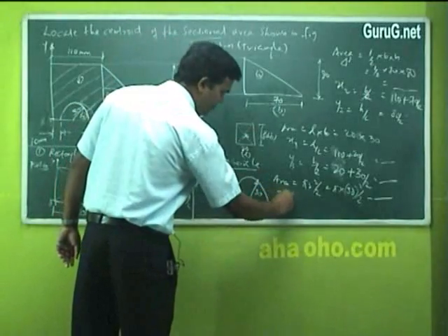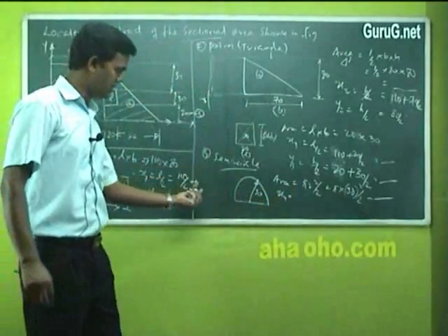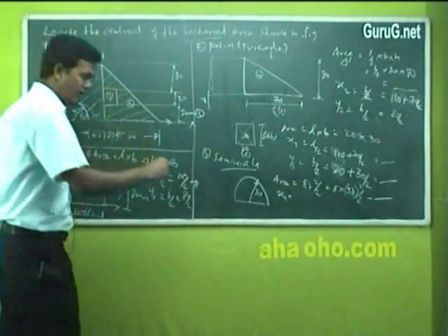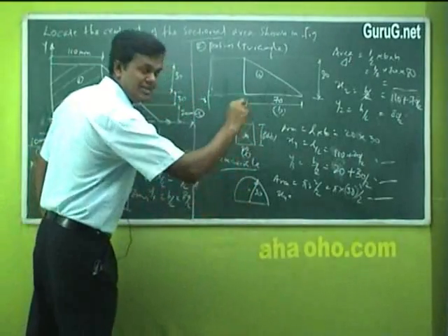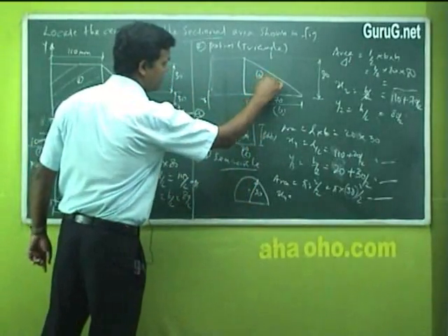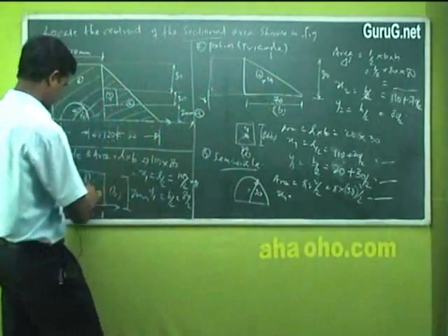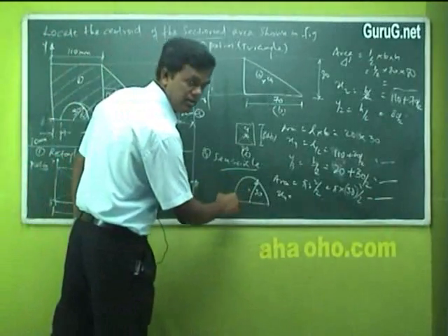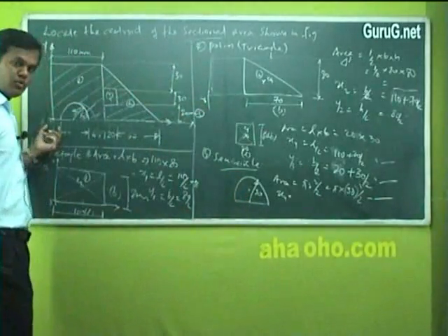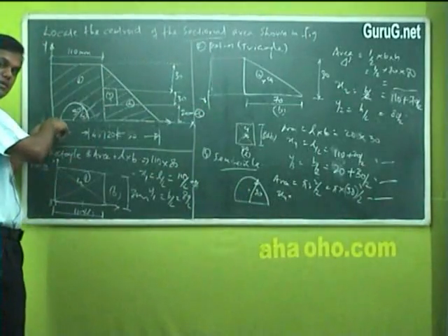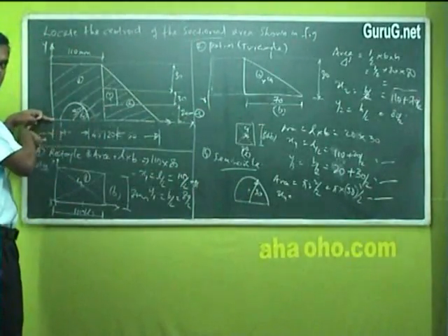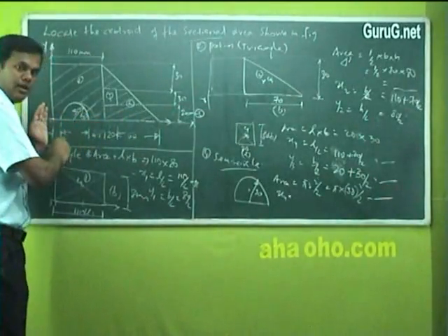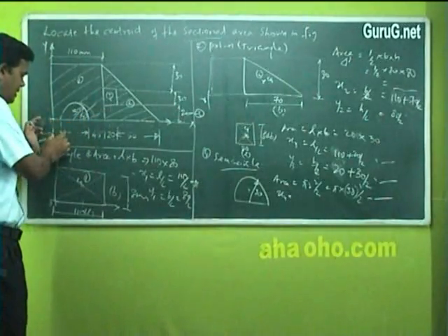Then x4. In the x direction, from the base, I am finding the center point. I am trying to find the individual CGs, individual centers of gravity, at all the places. So this is what? From here, to travel x, what is this? This sketch is drawn leaving 10 millimeter from the base. From this line I am traveling on the x-axis side. Hope you understand. From this side, leaving 10 millimeter, it starts.